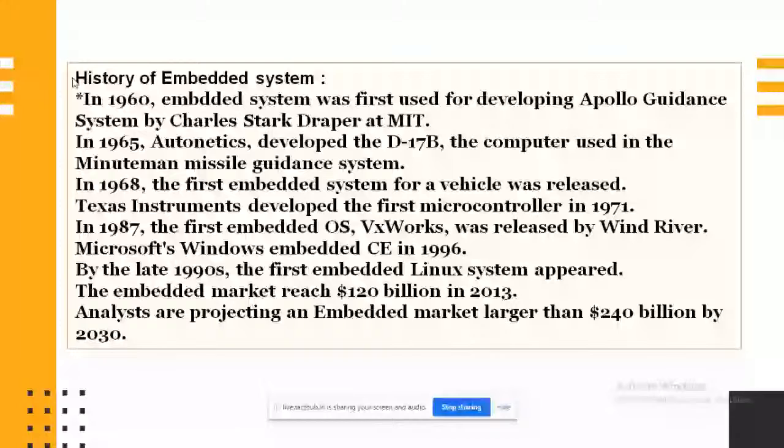They have I/O ports, counter, interrupt mechanism, RAM, ROM on it, and you can program it, but that is not the case with the microprocessor. You should have some peripheral devices like 8255, 8259, and other controllers to convert it into a computing device. But that is not the case with a microcontroller like Intel's first 8-bit 8051, and so on. Now ARM7 is also there.